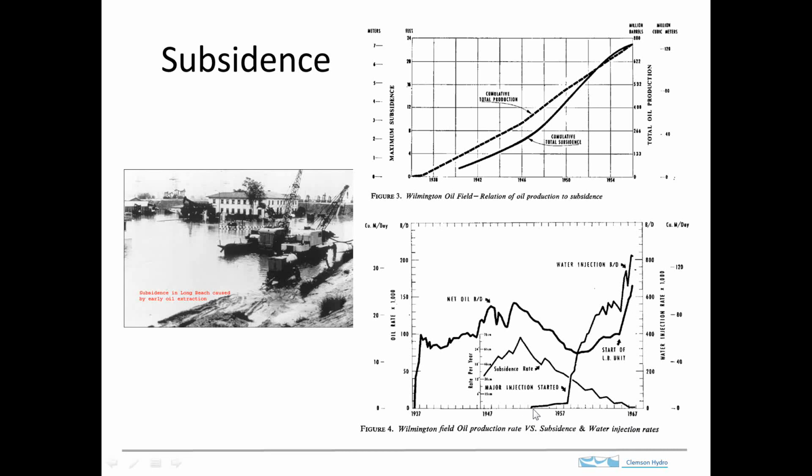And what happens is that here we have some decline in production, so the subsidence rate is declining because of that. But now the production starts to pick up, but they're injecting water, so the water injection boosts the pressure in the formation, and that, you can see, reduces the subsidence rate. So it hasn't reversed the rate by this point. We're not getting net uplift, so there still is this much loss of elevation, but the rate of subsidence has essentially stopped as a result of this water injection, at least as of this paper.